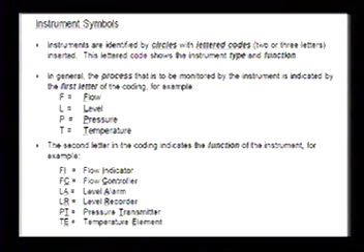You don't want to stick a piece of stainless steel in acid or something, or put some caustic material on something that would just eat it up. And obviously, if it's a high pressure line, you want to make sure all those fittings are rated for that high pressure line, not the subject here. But the temperature element actually screws into the pipe, and then your temperature transmitter screws onto that and slides into the temperature element.